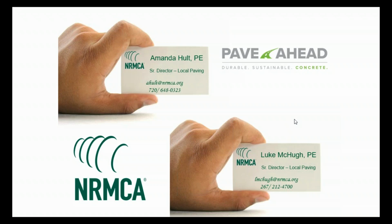The next question has to deal with soils. What are methods to increase the subgrade reaction modulus apart from increasing thickness of granular fill, specifically in areas with soft soils? Well, first of all, I do want to remind you, we have a nice soils webinar next Thursday put on by Brian Killingsworth, an hour and a half, to where I'm sure he's going to really dig into this. But the short answer that I have in the presentation, we talked about, yes, you can put in the aggregate underneath or on top of the soils to increase your K value. The other thing that you can do is cement treatments, and so that will then increase your K value as well.